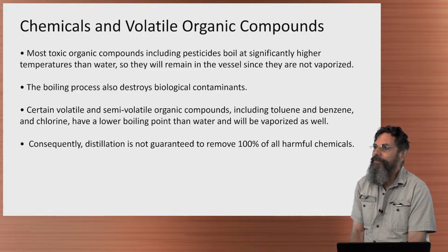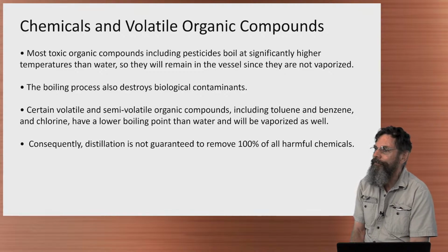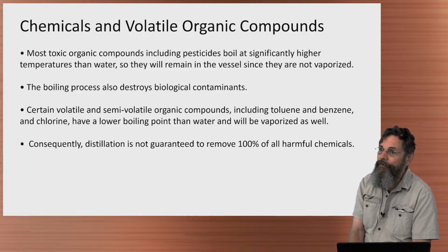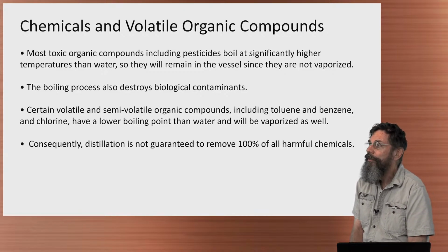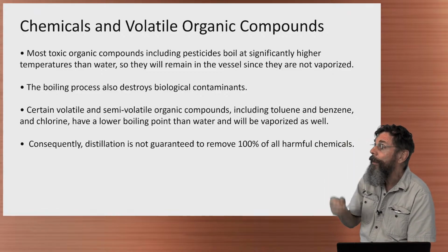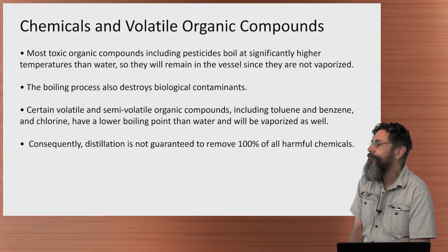So any water distillation system that you might see for sale that claims, without filtration, to guarantee 100% pure water coming out the spout is actually not being completely honest, because if there happens to be a toluene or a benzene or chlorine in the water, so if you took your tap water, which is chlorinated from the city water tap, and put it through the home distiller, it's still not going to remove the chlorine, because the chlorine boils off at a lower temperature. So on our way up from 65 degrees out of the tap up to 100, 150, 175, where it's going to start to vaporize a little bit, and then on up to 212, that chlorine is going to, and the benzene and anything else that might be in there, is going to vaporize and get processed and extracted right along with the pure water. So the water isn't pure.